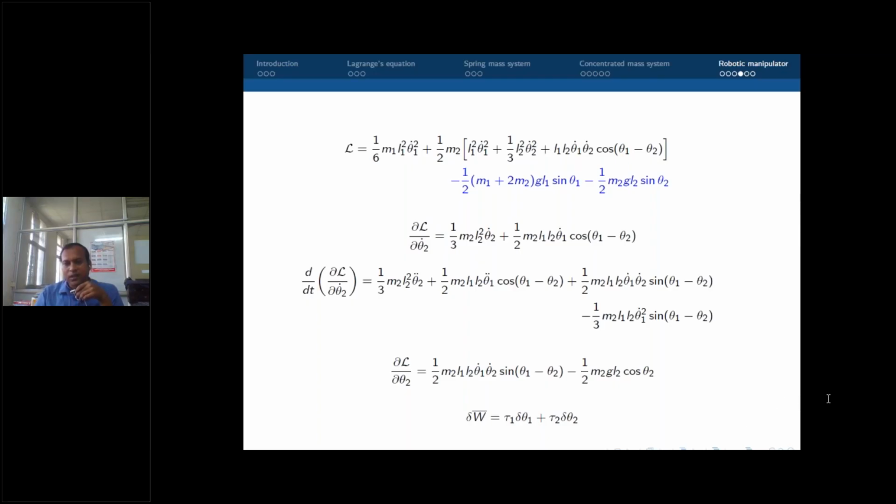Sir, can you please give me an idea how to study dynamics and kinematics of a wheeled mobile robot? See, I do not have expertise in wheeled mobile robots. I have done work on dynamics, and vibration is my field. But it is not different. This is the basic idea. You have a problem. You can just model it, and then you write down the equations of motion. You have a joint. Once you have a joint, you know what degree of freedom is allowed. Then you define the required coordinate system. Once you have defined that, write down the kinetic energy, potential energy, everything is done.